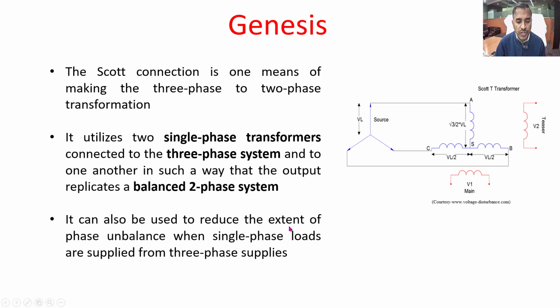It can also be used to reduce the extent of phase imbalance when single-phase loads are supplied from three-phase supplies. So when single-phase loads are supplied from three-phase supplies, if we use Scott connection, then it reduces the extent of unbalance. So the Scott connection is shown here typically.